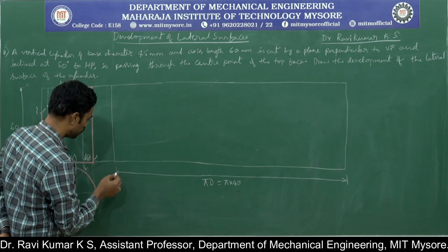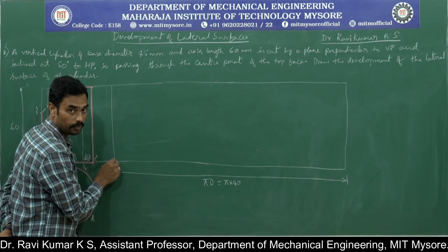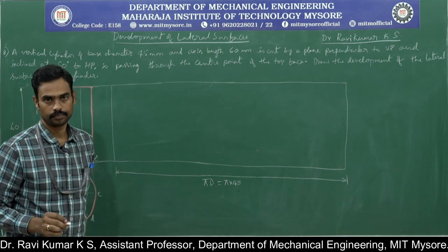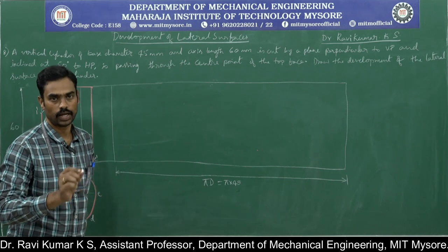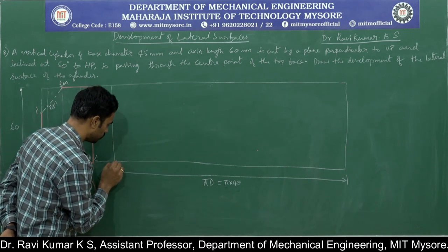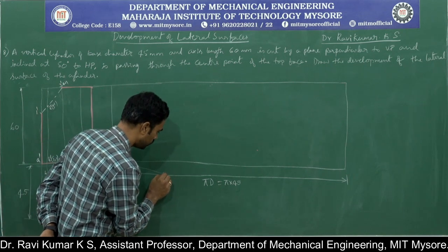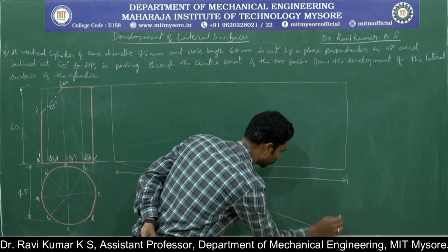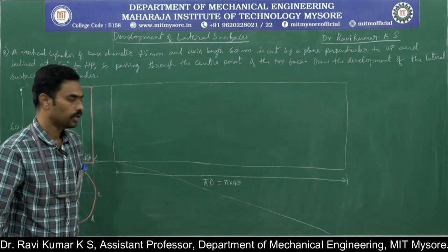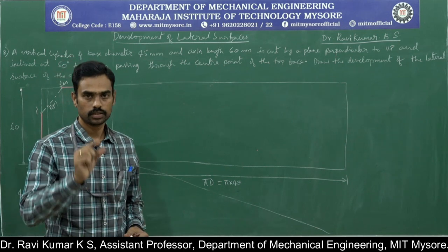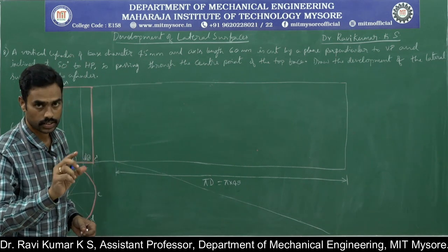You just concentrate here. Select this particular point, draw a line with any acute angle. Acute angle means less than 90 degrees. Any acute angle. So I am drawing a line here with any acute angle like this. Now take the compass, any distance. In your compass, take any distance.